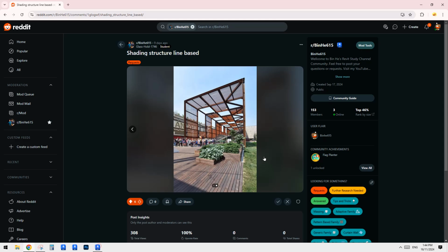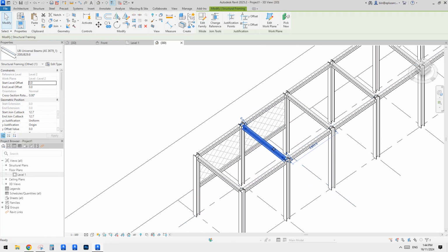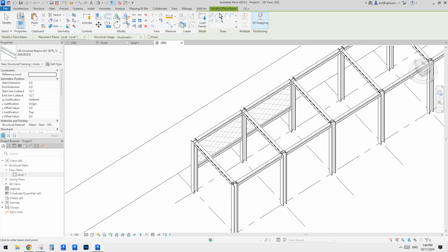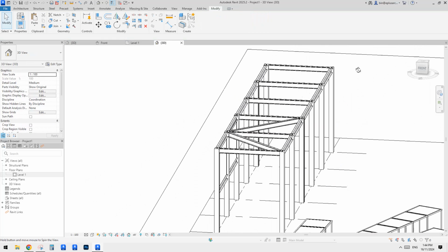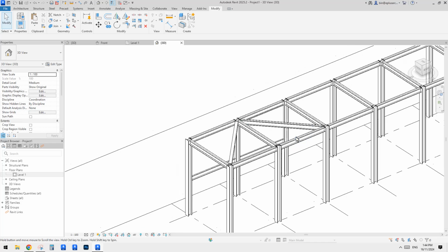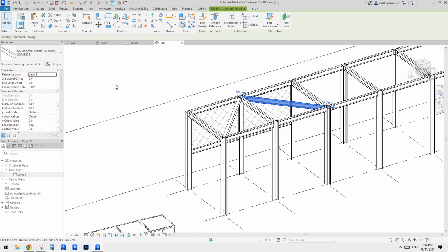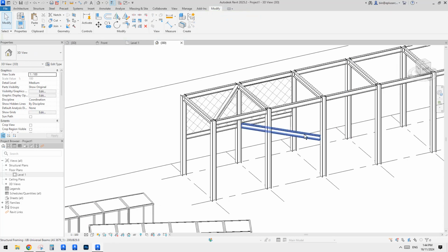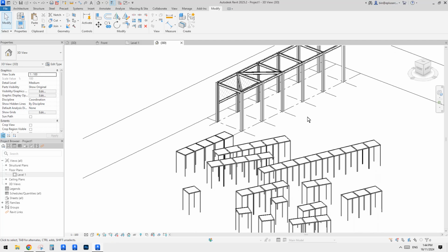And also the last thing is all these diagonal columns. They are very simple. You can just create a structural beam, CS, create similar. You can always use 3D snapping. For example, I'll do something like this, from this to here, right? And then if you want to move it to this level, you can change this one to level 1, 2 meter, and also 2 meter. It will go down to that level. Okay. Let me just Control Z, and this is it.